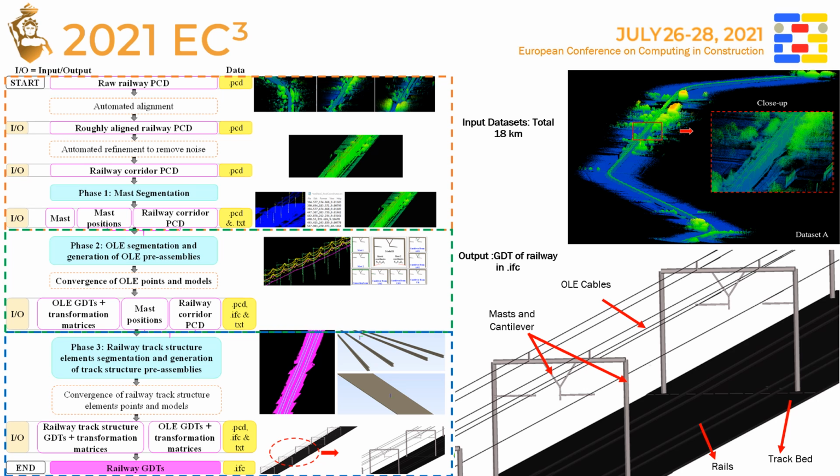length. Railways are linear asset types with standard geometric patterns, so their geometric relations remain roughly unchanged, often over very long distances. The close inspection of railway point clouds validates this effect with repeating geometrical features. So we use these features as assumptions in our proposed framework.